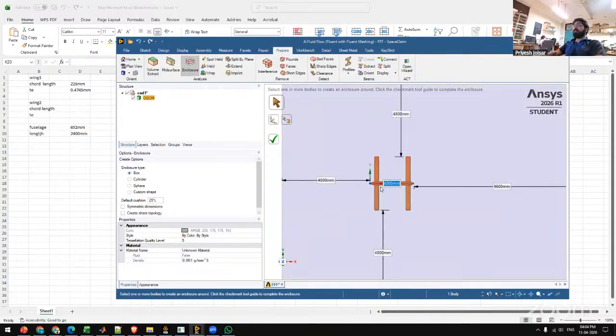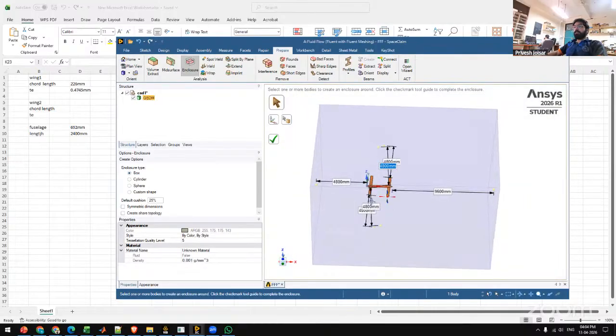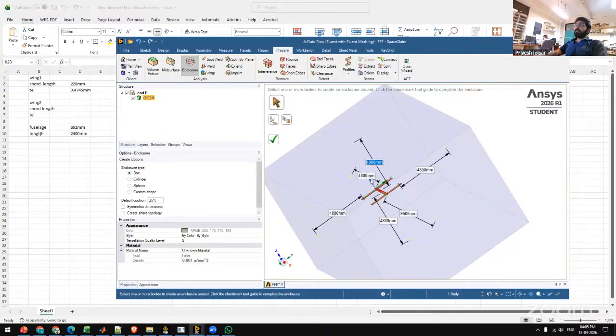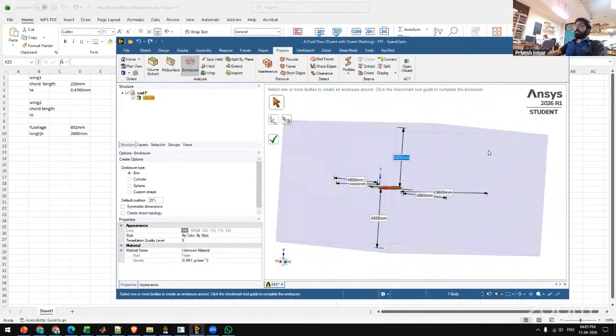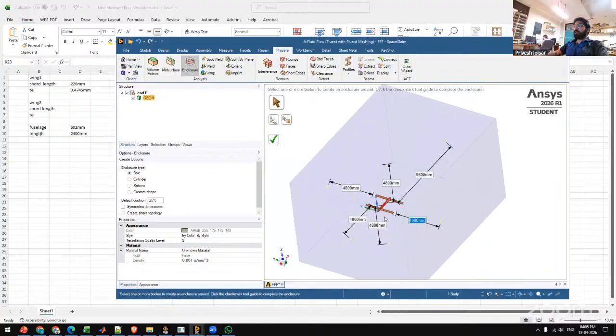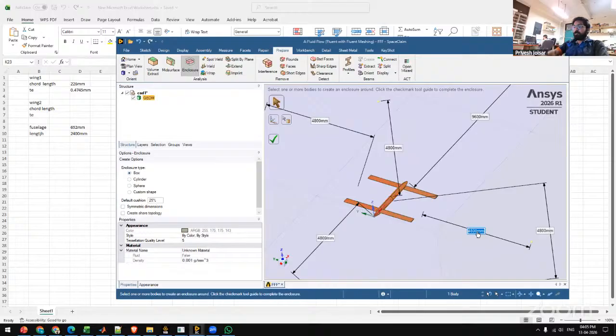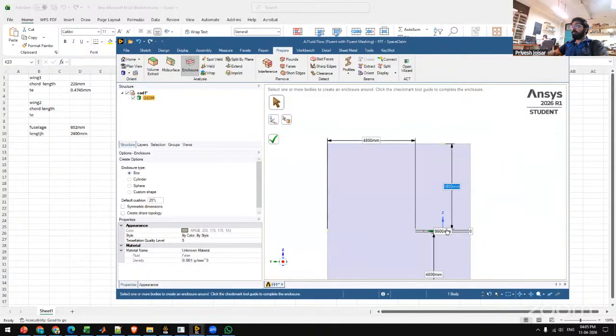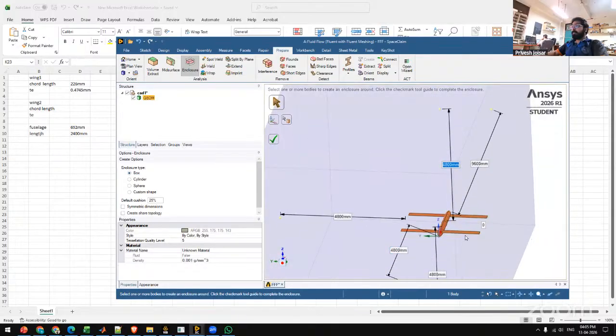So we can always have a domain size which is symmetric to the Z and X axis. So we can reduce the number of cells and have faster calculation. So I'll choose a symmetrical boundary condition over here and reduce this to, let's say, 0 as of now, and then we'll change the length accordingly. Or I'll better cut it down.